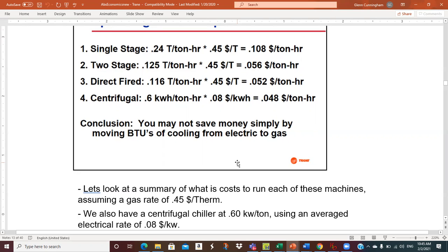That comes up to say 293, and then you multiply that times 0.08. So that electricity, on a million BTU basis, is $23.44. We can buy natural gas for $4.50 a million. And when we buy electricity, it costs us $23.44 a million.